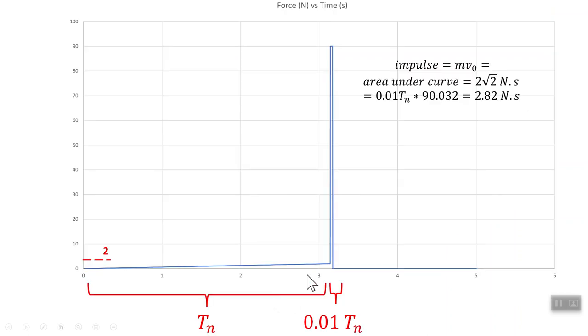So the way I did my second video, where I modeled initial velocity, I used the concept of impulse. So the force modulation that will be defined in Catia is a curve like this. Initially everything is 0, and over one period, which is very slowly, the mass is pulled to the right, for example, so that it reaches that position of 0.5 meters. Now, 0.5 meter multiplied by the stiffness of the spring gives you 2 newtons.